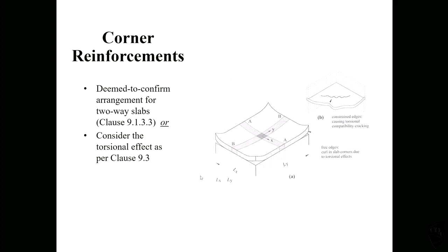You calculate the bending moment diagram using clause 6.10, but there is a different table for two-way slabs. Once you have that, you should be able to design the flexural reinforcement for AA direction and BB direction. 2 separate designs. Repeated calculation with some numbers different.